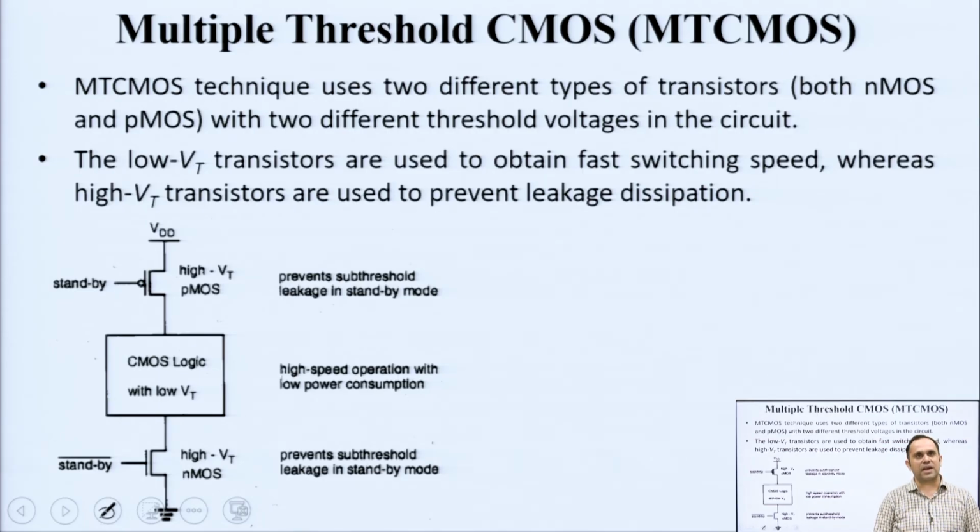So, without making any design changes, you have actually influenced the threshold voltage of the device. These techniques allow you to use low threshold voltage circuits, make use of their benefits on delay and power, and at the same time control the subthreshold conduction.